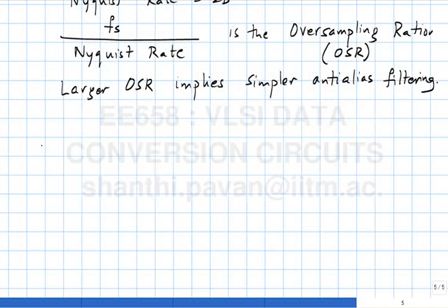And it turns out that when the sampling rates are extremely high, you will find that there is a finite speed associated with transistors, so they're just not able to do whatever they're supposed to do at very, very high rates. So in other words, there is a finite limit to the rate at which you can sample in practice. And clearly this depends on the speed of the transistors. So if the transistors are fast, presumably you can sample faster.